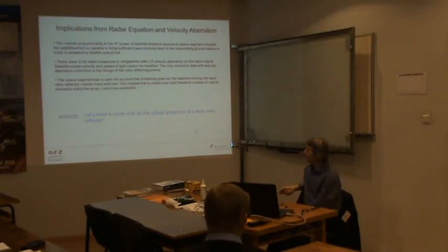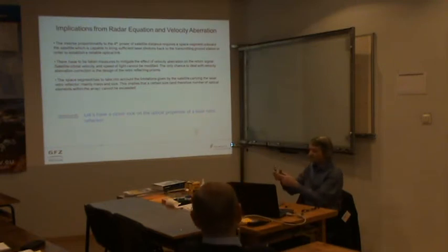The reason why the spacefaring agencies like laser retroreflectors is that they are relatively small and relatively low in mass, practically very low masses and sizes. They do not need power from the onboard power supply system. They do not need thermal regulation, and they do not need any radio contact, no radio link, no connection to the onboard computer. But a certain size and number of optical elements cannot be exceeded.